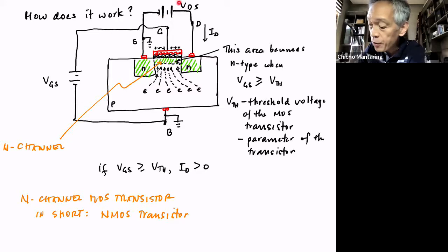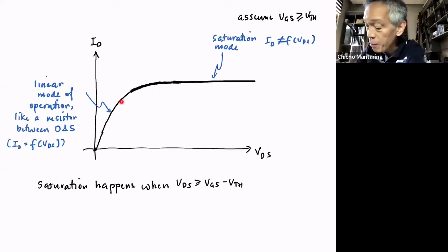This value of VDS actually has an effect on the electric field here. It doesn't seem so, but it does. So the larger the value of VDS, the smaller this electric field becomes. At some point, the electric field will become almost so small that your current will no longer increase. So yun yung rason kung bakit at some point nagiging constant na to. That's as far as I want to explain it. You're going to learn the real explanation in your future semiconductor physics courses.